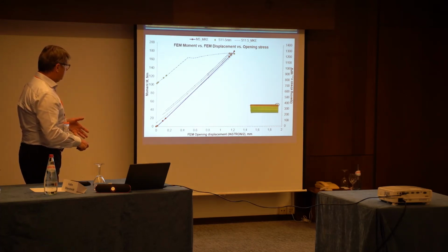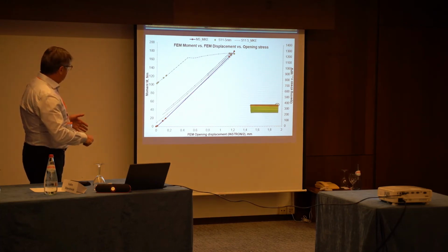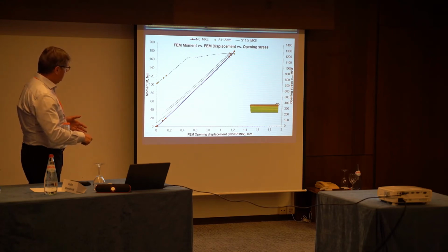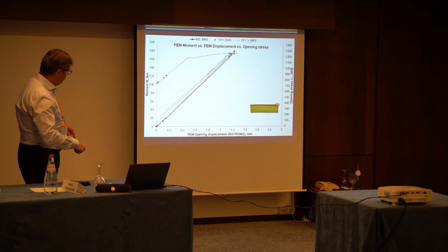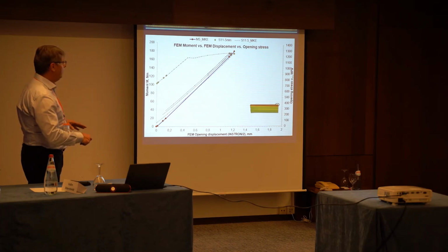Moment was this blue violet line, and here you have already started with residual stresses, and this is the linear, let's say, loading path. So you start from here, and immediately you have this stress, and when you come to this point, you are already with this opening displacement, you are already in this plateau, and if you continue, you will remain on this plateau.